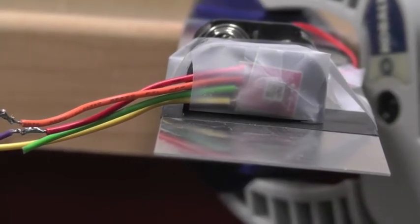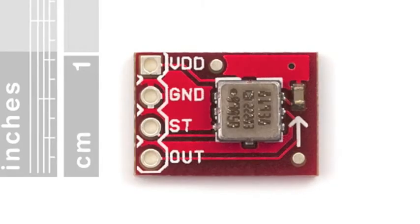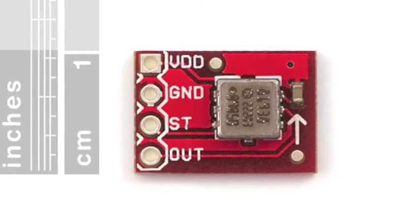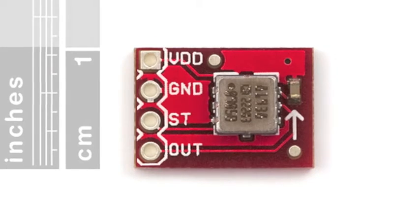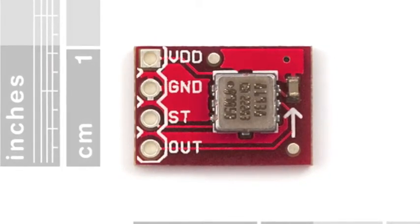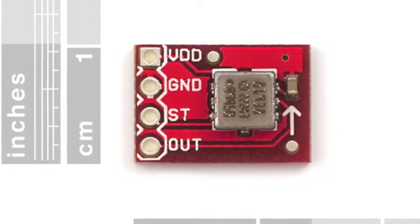The wires that you see must be soldered to the accelerometer and connected to the Arduino board. Information on how to properly make these connections can be found in your assignment and in the accelerometer datasheet. You can also find a brief tutorial video on proper soldering technique in the resources section of your assignment. The breakout board on which the accelerometer is mounted essentially replaces the breadboard circuit that you see in your assignment. This allows for direct connection between the accelerometer and the Arduino.